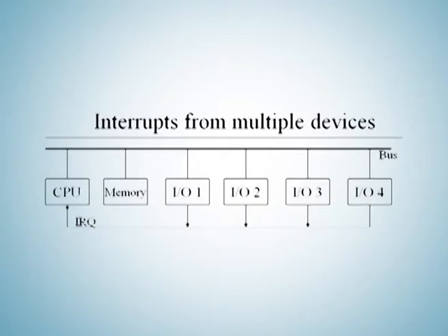The next design issue is how to handle multiple interrupts. When there are n I/O modules connected to n interrupts provided on the CPU chip, the process of identifying the requesting I/O module is simple and straightforward. However, when there are many I/O modules connected over limited interrupt pins, techniques are needed to identify the requesting I/O module. There are several techniques to identify the requesting I/O module. These techniques also provide a way of assigning priorities when more than one device is requesting interrupt service.